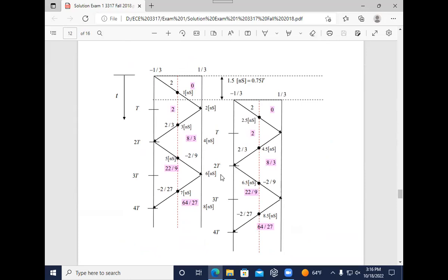Correct. Well, in the oscilloscope trace, remember you're making vertical lines, so you need these two vertical lines. That's probably why we did it like this. But in my opinion, the easiest way to make the oscilloscope trace is instead of doing two vertical lines, just use this one here. Make the final oscilloscope trace using only one bounce diagram.